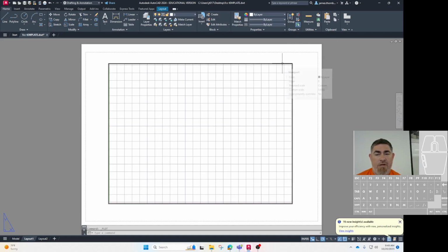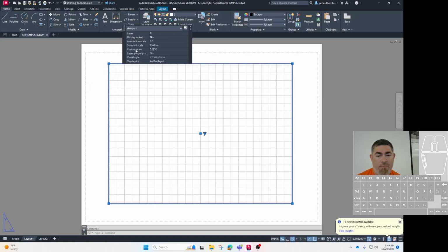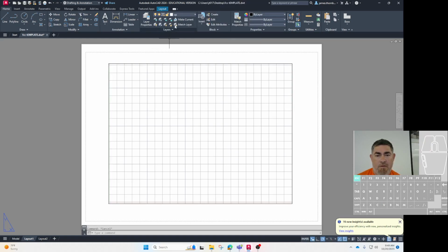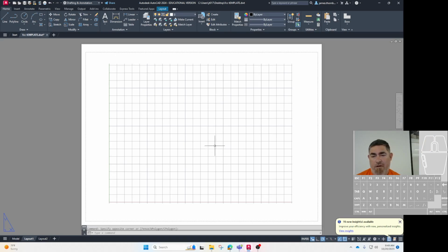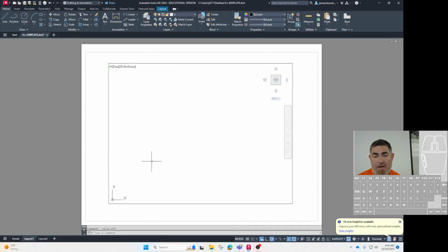Here's the viewport. We can just kind of ignore this for now. So if you have it on the viewport layer, so if you make that viewport layer, you click that, put it on that viewport layer, and then just turn off that viewport layer, and the viewport will go away. You'll still see the grid back there. Double click and it'll go in. We'll talk more about how to use that later.